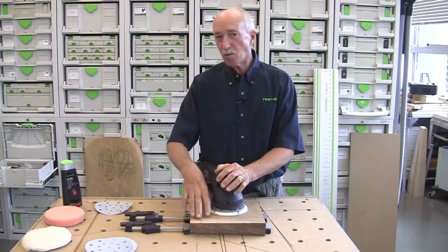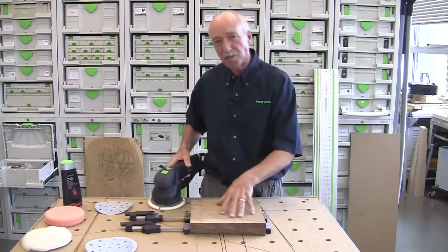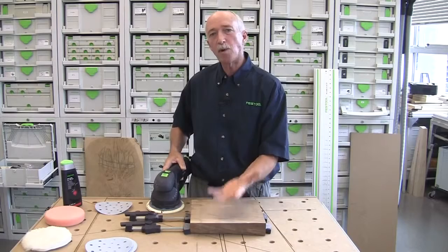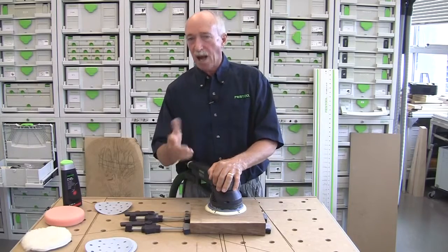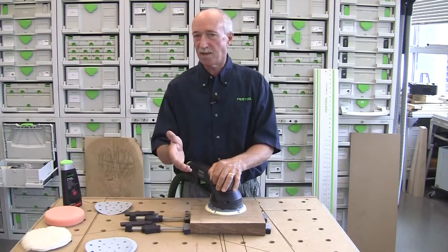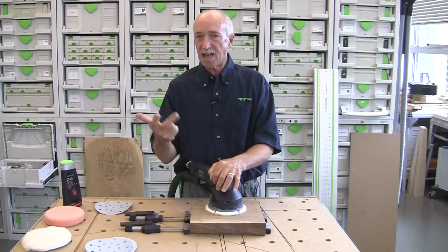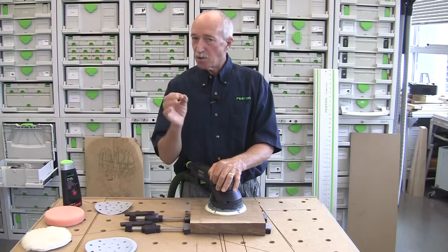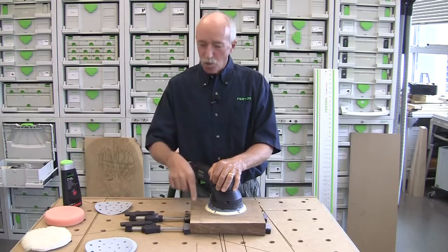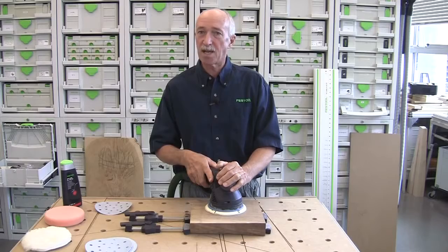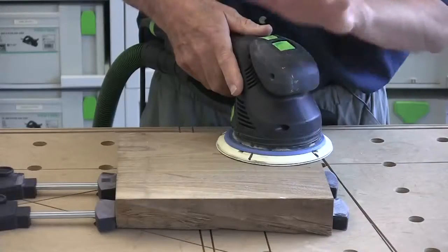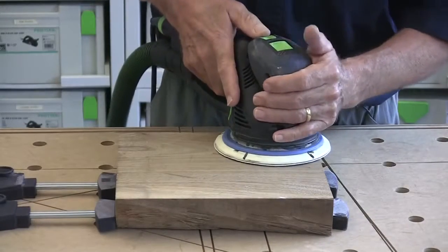We're going to start with 40 grit to really scratch this beautiful piece of black walnut, and then we're going to bring it up to a beautiful finish. But if I start with 40, I can't go from 40 to 150. I'm going to go 40, 60, 80, 120. If you skip grits on the low end, you will not get deep enough to get those deep scratches out. That's a common mistake that many sanders make. So let's start with the 40 grit in Rotex.